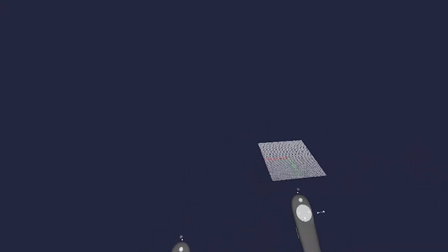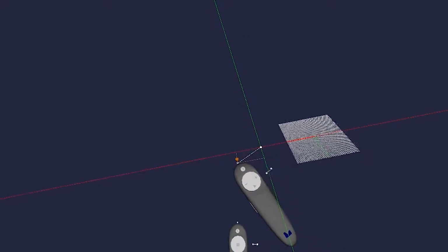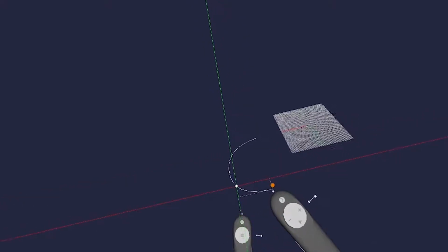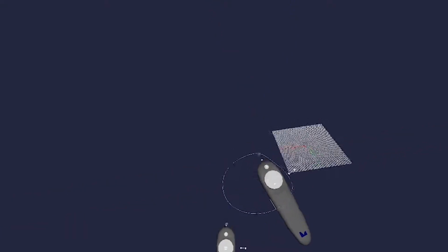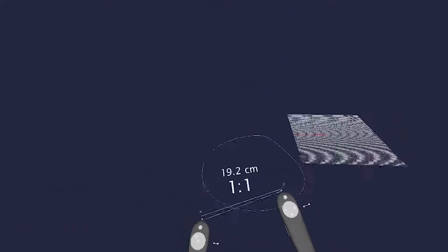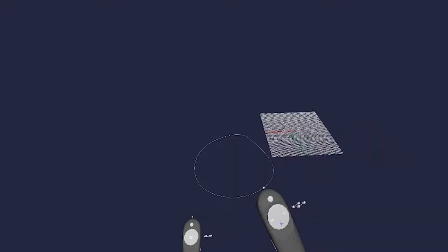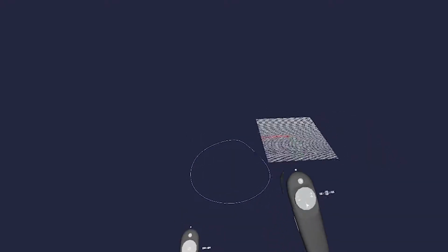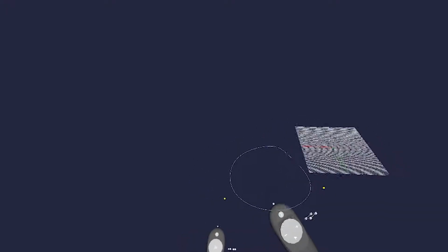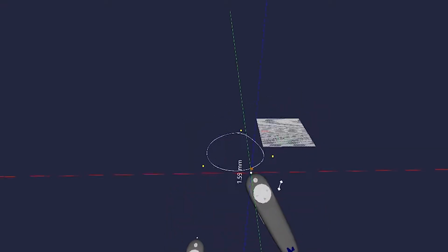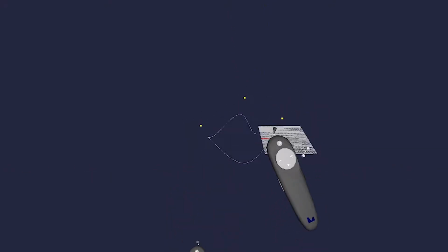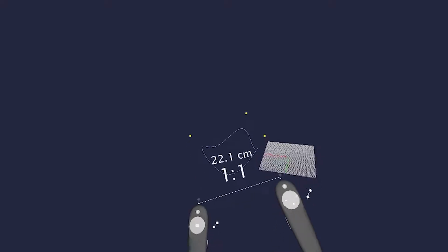Today we're going to go over 4 new design tools. Once you launch the app, select the spline tool and create a flat, closed loop. Next, turn on the points and select a few of them that we're going to bring up vertically to create a 3-dimensional line. Make sure you stay in line with the Z or blue axes.